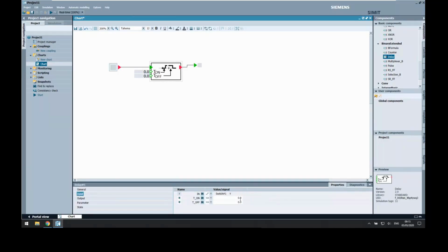So for our delay, we can either change the time for the on delay from an external source, or, and this is what I'm going to do in this case, we can just punch in a number. So for me, a delay of 5 seconds. If my PLC code switches a device on, I expect this device to be on after 5 seconds and to provide the signal back to my PLC code.